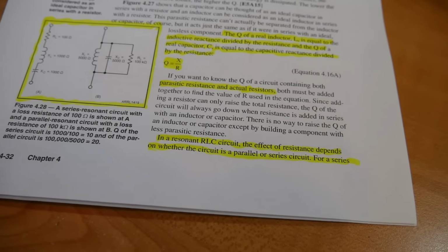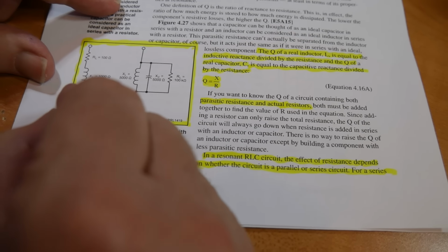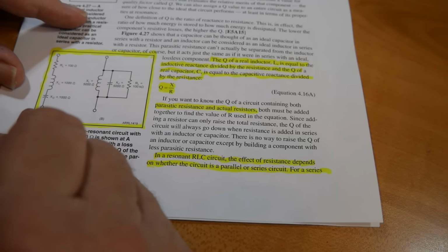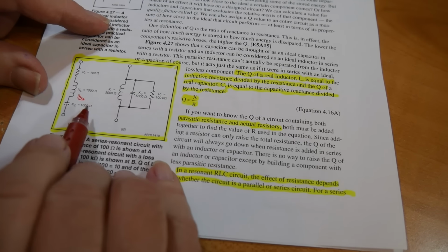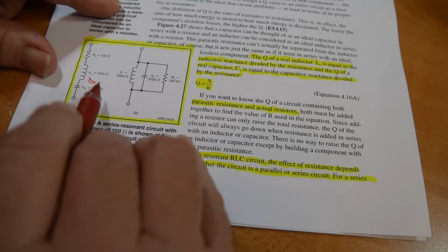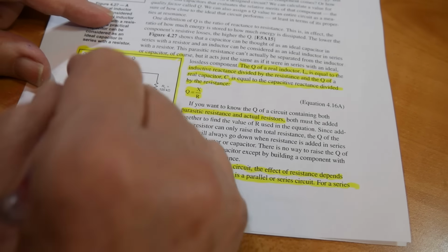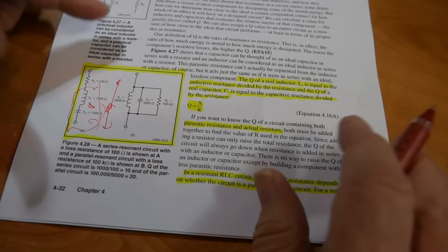If you look down here at this diagram, which is the one that you found confusing, please note that we've got a resistance here of 100 ohms. We've got a reactance of 1,000 ohms, and this reactance has to be 1,000 ohms too. Why? Because this circuit is given to us as resonant. So this will equal that in magnitude, not in direction. Because the X sub L points down, the X sub C points up. They're opposite each other. That adds to 0 reactance, which makes this circuit resonant, but we see the values there pop up again.